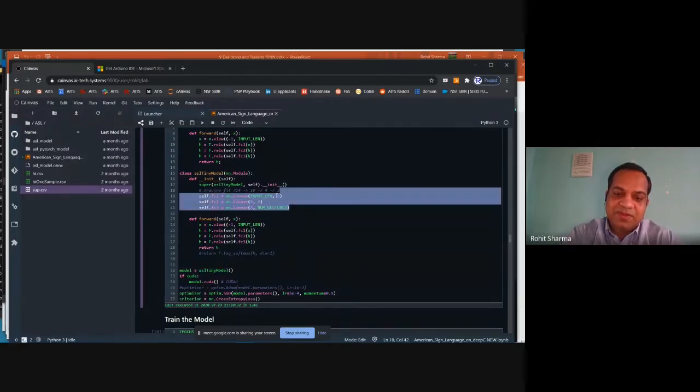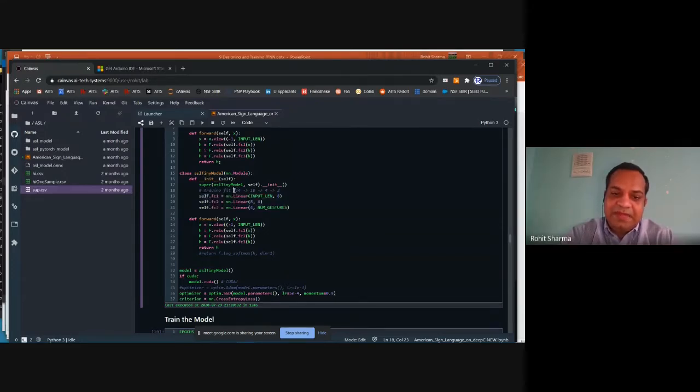The first one is your input layer, which is 714. And we have created a model that takes 714 samples, and 714 comes from the frequency of this board, which is 119 samples per second. There are 6 variables. So 119 times 6 is 714. So we are taking 1 sample per second, and that's what this 714 number comes from. So that's your input layer.